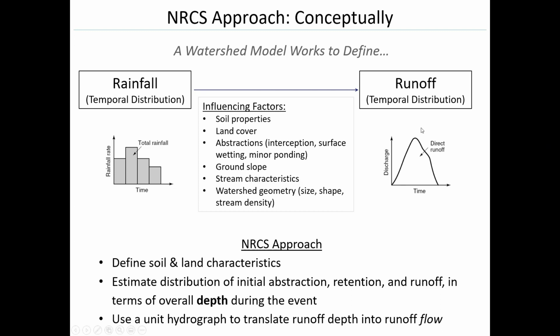It's just going to say how many inches of precipitation excess there is. And then you take that precipitation excess that's predicted and run it through the unit hydrograph, which we talked about in 2 previous classes, to get the flow rate.